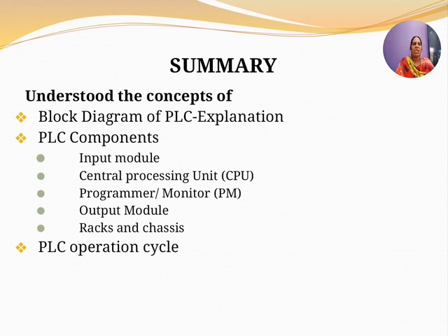So the input devices of the PLC can be either analog devices or digital devices. Analog devices are sensors like thermocouples, thermistors, tachos, pressure transducers, flow meters and level sensors. The digital devices can be push button or a selector switch or a limit switch or level switches or photo sensors or proximity sensors. Coming to the output devices of the PLCs, they are relays, contactors, solenoid coils, motor starters, lamps and horns.